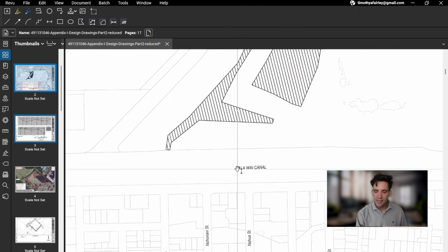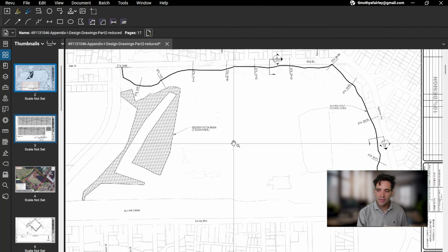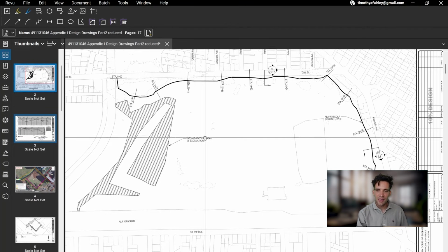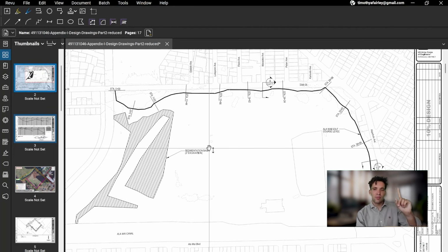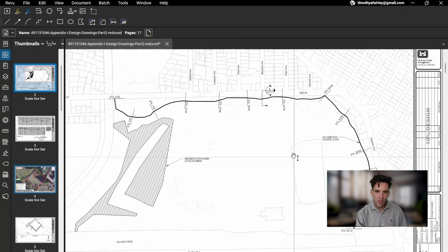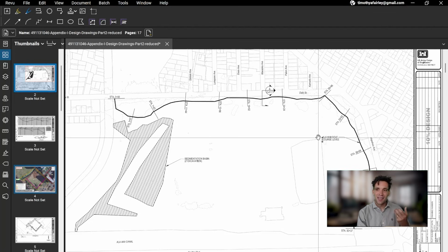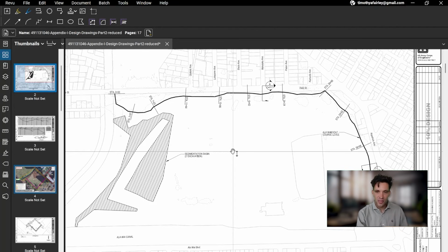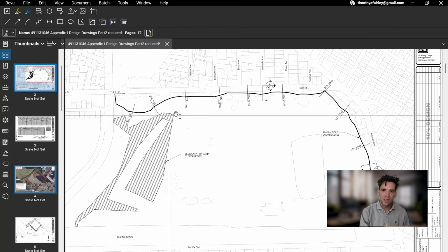When I look at this, the key questions we would then have is the volume that we're excavating out of here and excavating out of here. Also, number one with the clearing and grubbing would be the volumes of the topsoil and the cost of disposing of the topsoil and the clearing and grubbing. You'd also want to understand, is it just grass, or can you do it with an excavator, or would you need to actually cut down a whole lot of trees because that would have a bigger cost associated with it?